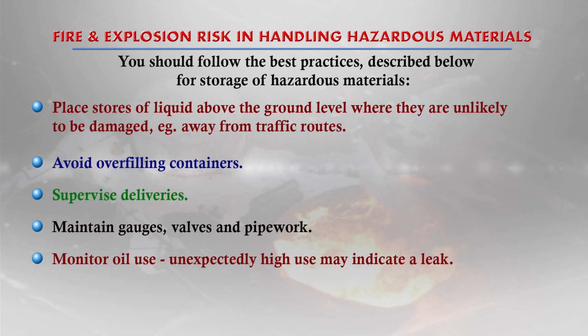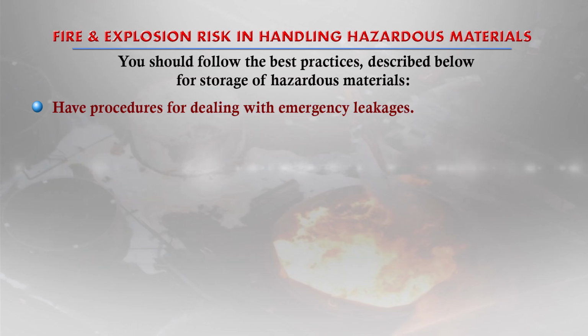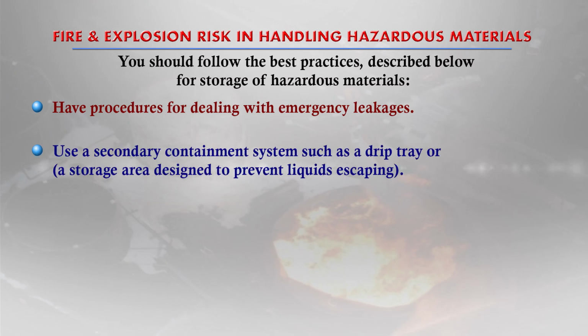Monitor oil use. Unexpectedly high use may indicate a leak. Have a procedure for dealing with emergency leakages. Use a secondary containment system such as a drip tray or bund storage area designed to prevent liquids escaping.